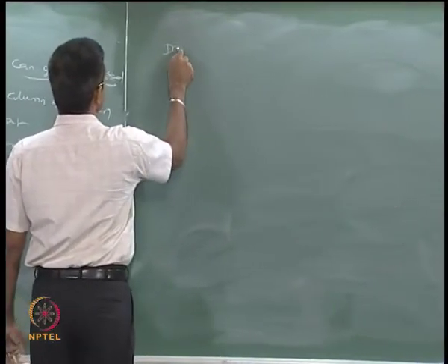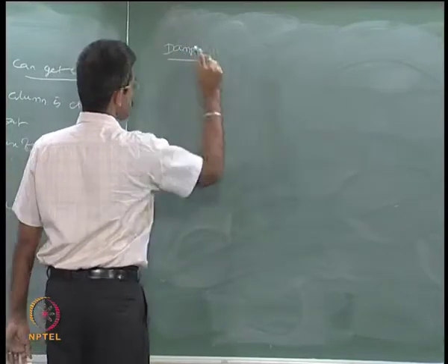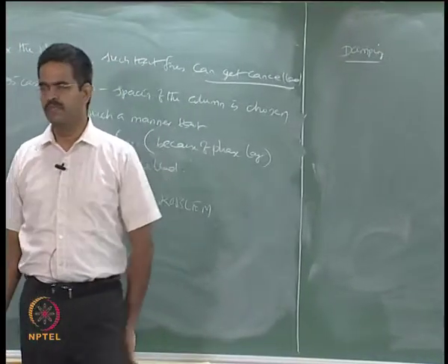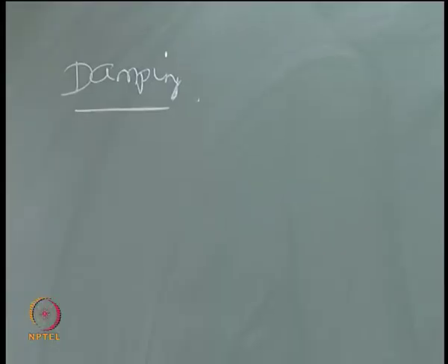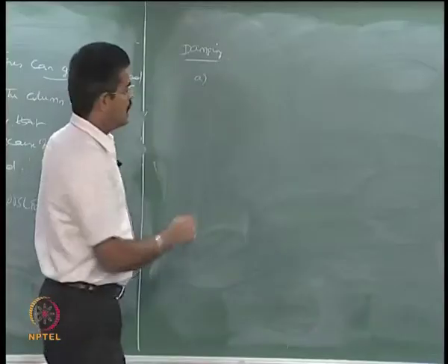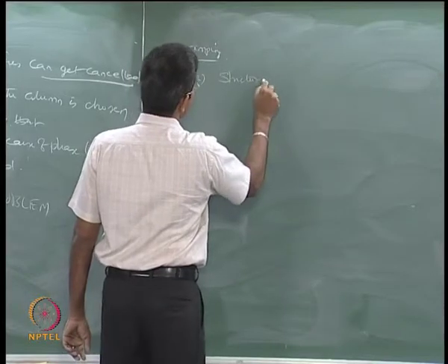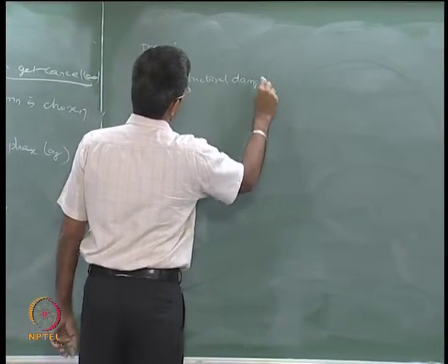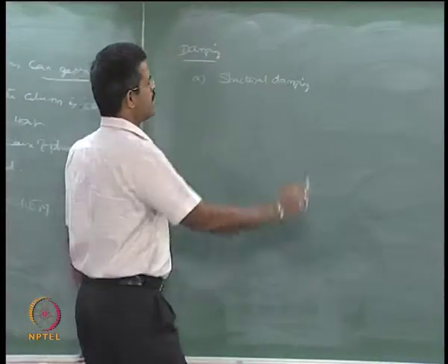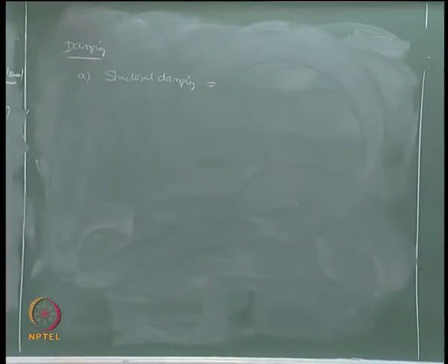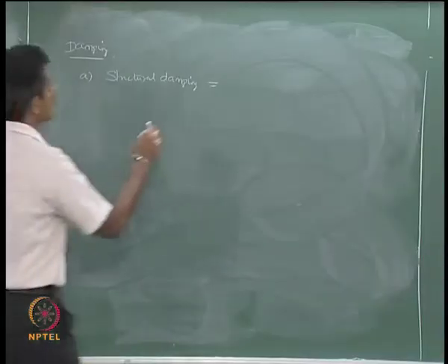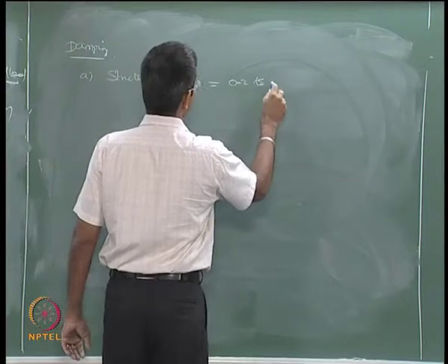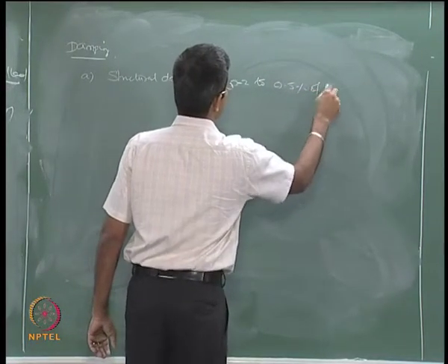The other important aspect is the damping force. The first of its kind comes from the structural damping, which is generally taken as 0.2 to 0.5% of the critical.